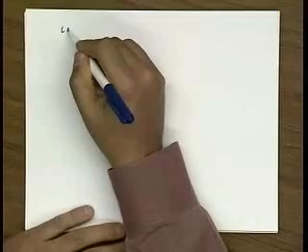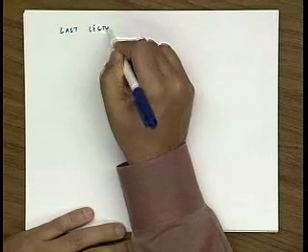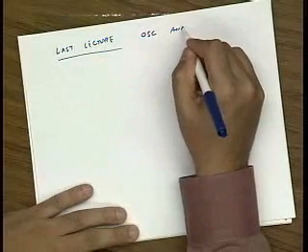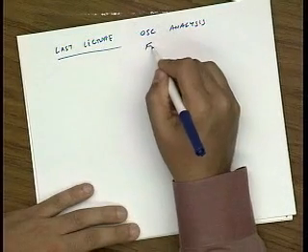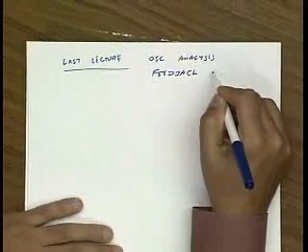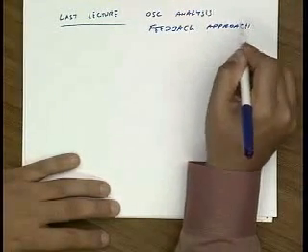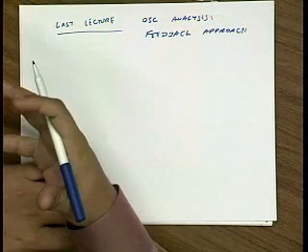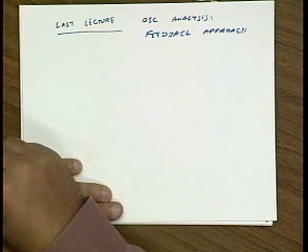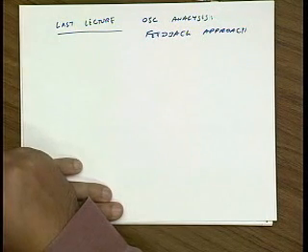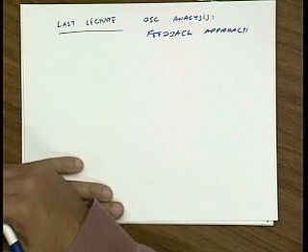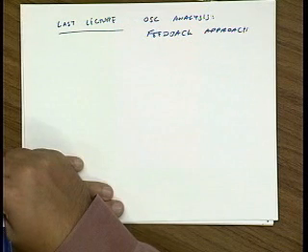All right, so let's summarize what we did last lecture. We used the feedback approach to find the conditions under which an oscillator, or a circuit in general, will become unstable, more specifically a tuned circuit, and how we could place its initial poles in the right half plane so that any kind of disturbance in the system would cause these poles to ring and grow in amplitude.